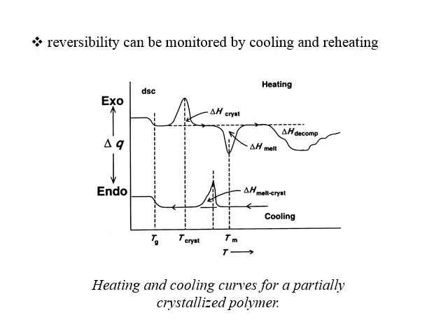Reversibility can also be checked on a DSC. So here's an example of some kind of a crystallized polymer. Note on this particular DSC plot, it is indicated exotherm up, endotherm down. dQ, or delta Q, being the heat, or the change in the heat. So we have an initial heating of the polymer, which shows up as a Tg. So there's the Tg on the initial heating, followed by an exothermic event.